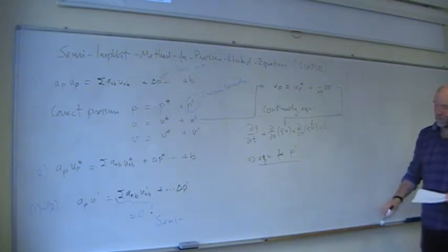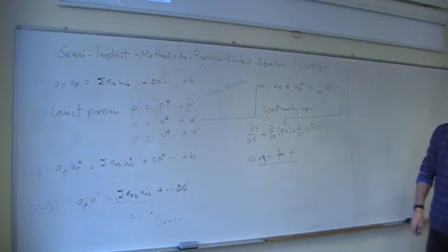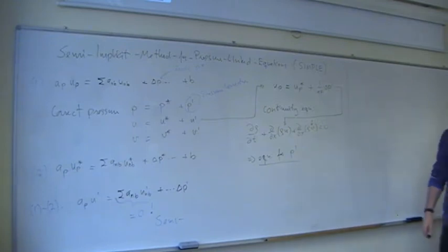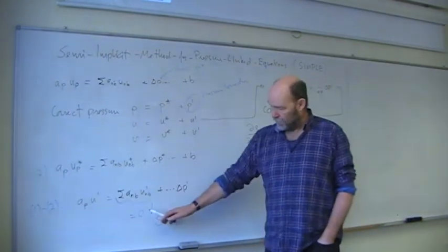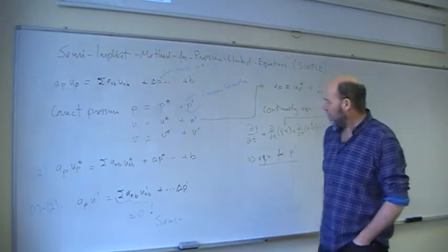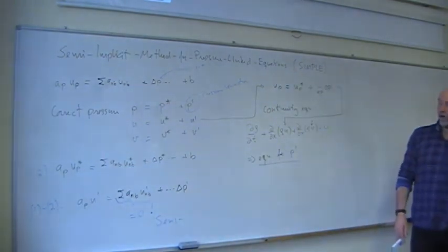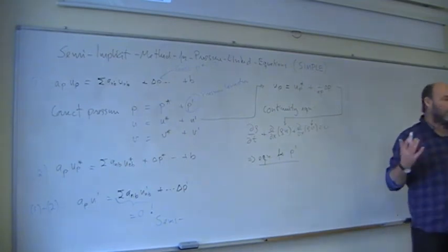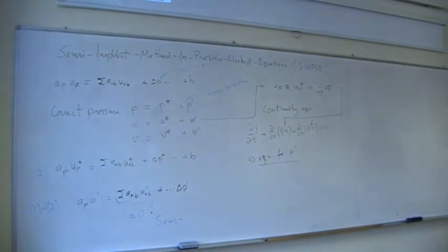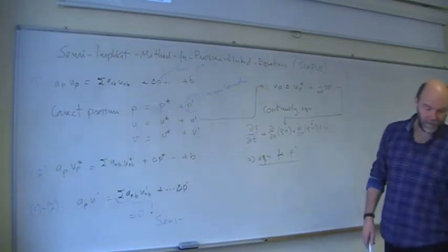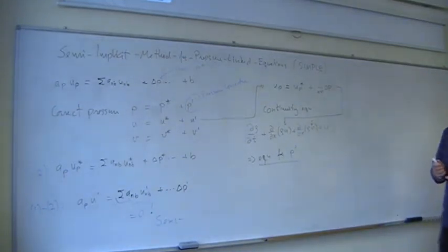And since it's semi-implicit, yes, you have to iterate. You can't solve it directly. If you had kept this, don't say that this is 0, then you would have ended up with a direct method in the end. So somewhere along the line here you have to choose. So the first success, that was this SIMPLE, how to solve this pressure linked equation system, velocity and pressure.